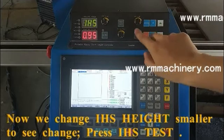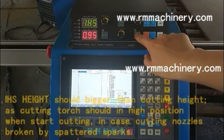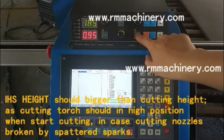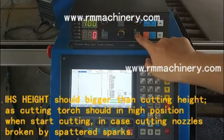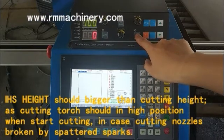Press IHS test. IHS height should be bigger than cutting height, as cutting torch should be in high position when start cutting, in case cutting nozzles are broken by spattered sparks.